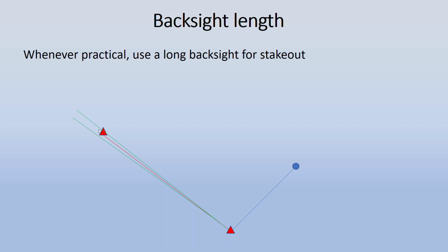On a modern total station, the angular accuracies are typically 5 angular seconds or less, and we can definitely live with that on a construction stakeout job. So when we turn our angle to our foresight, that same tolerance window gets projected over there. And if our foresight distance is shorter than our backsight distance, that tolerance window is proportionately smaller.